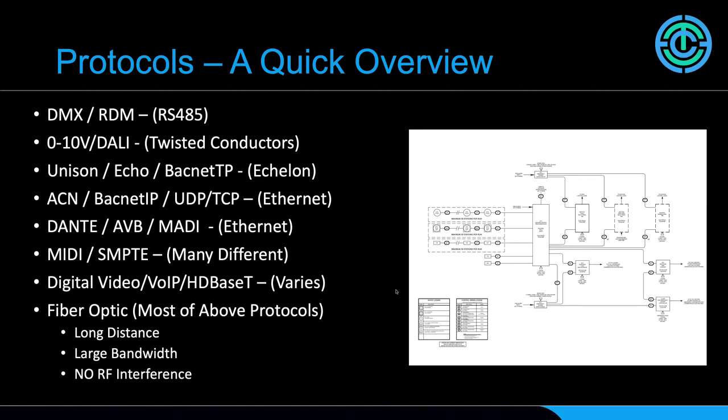The one major benefit that fiber has also, though, is that it has very, very high resilience to RF interference. Fiber optic cable, being a light transmission medium, can run large distances along power lines, along other RF transmitters, and not be affected. So something to think about when you're looking at your systems design. Someone may say fiber. Fiber has actually gotten quite economical, quite easy to terminate, and quite robust in use in AV integration systems or building systems.